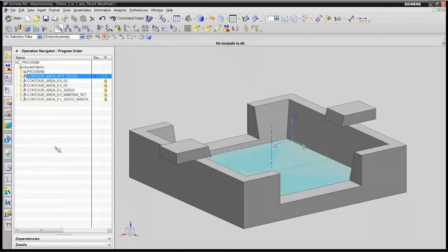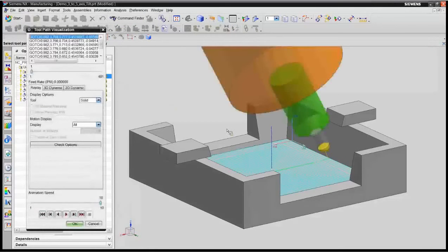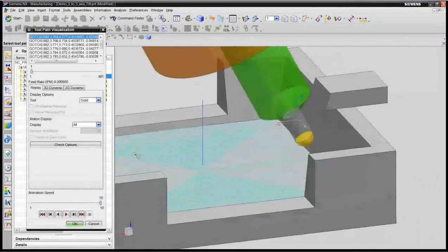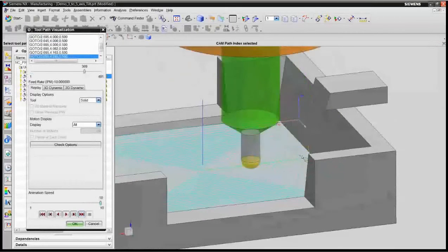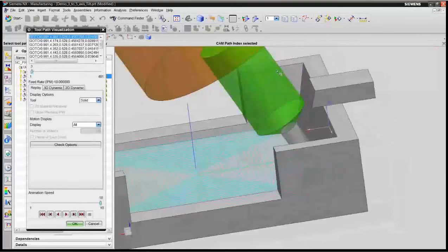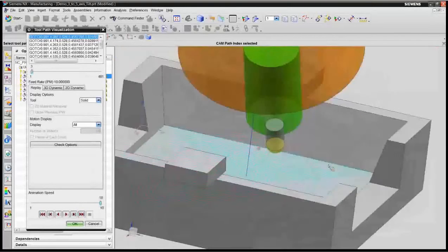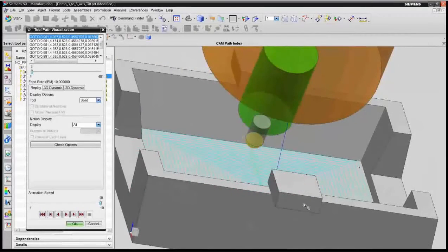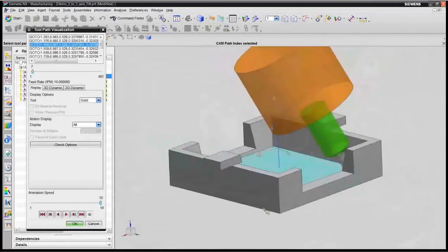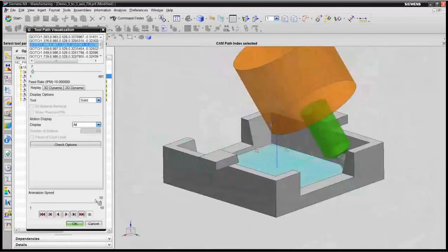This toolpath that was already created, that quickly, I now have a 5-axis toolpath. And if you notice, we are now tilted enough to clear the clamps, so the holder is not colliding with the clamps. And as we get over here into the corners, it's tilting both directions away from the part also.